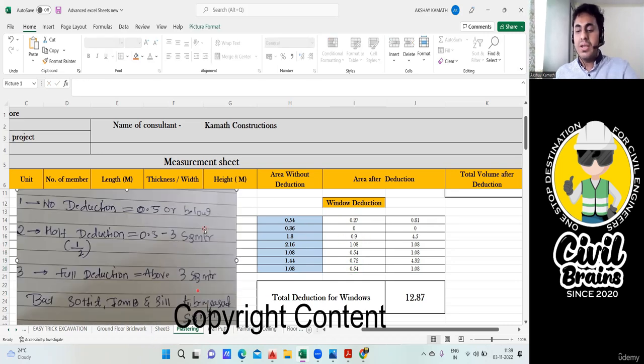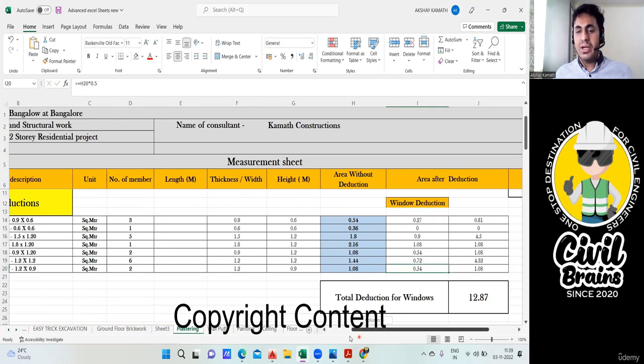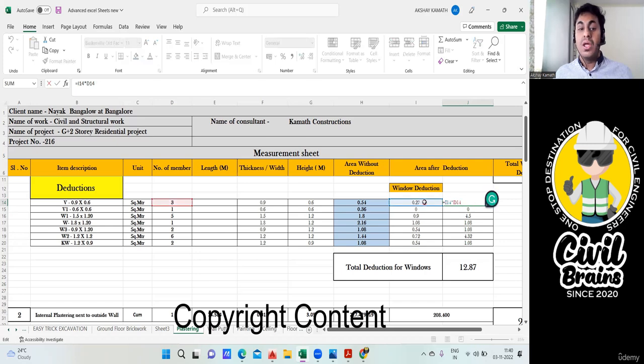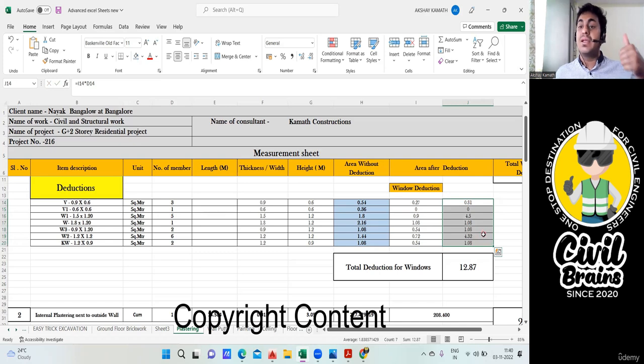Now, that is why I have done this for one window. Understood, no? This is for one window I did. This portion 0.27 is for one window. Okay. Now this I'll multiply by total. That is 0.27. How many ventilators are there? Three are there. So I'll multiply it by 3. Getting my point? Of course, this remains 0. Again, this portion, 0.9. How many W1 windows are there? 5. So I've written 5 here. Okay. So this is the total area of deduction of all your ventilators and windows.